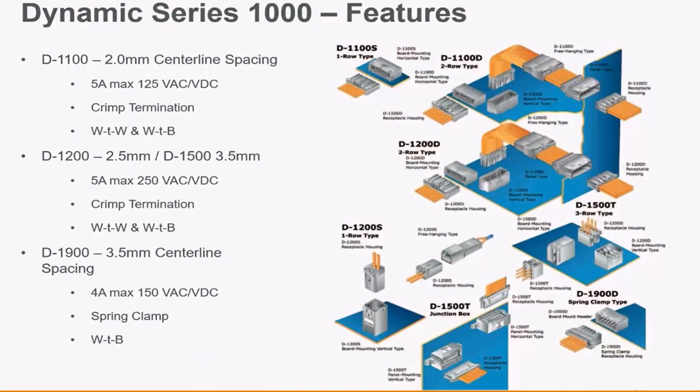The choice between gold and tin plating offers a cost-effective solution, as both materials are good conductors. Firstly, it's important to note that both gold and tin are excellent conductors. The choice between these plating options is influenced by cost considerations. But also, tin plating can withstand higher temperatures, making it more commonly used in power applications. On the other hand, gold-plated contacts are ideal for signal applications due to their excellent conductivity.